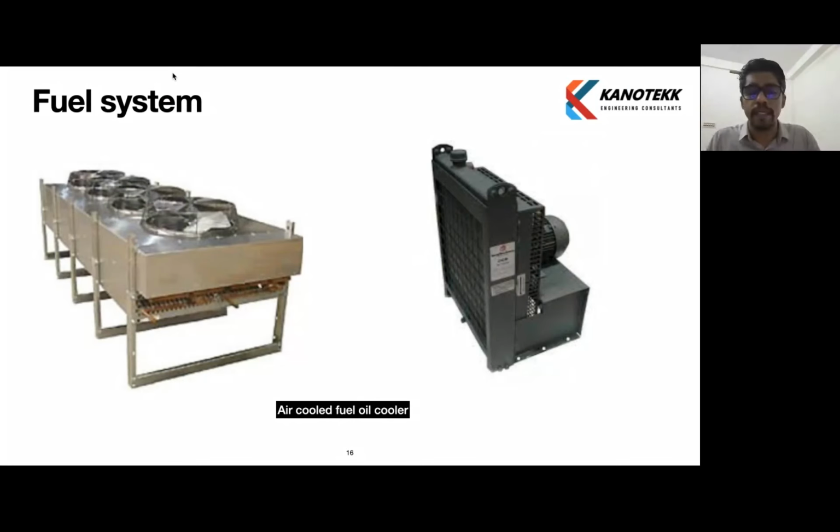Okay, what we are seeing is air-cooled fuel coolers. These fuel coolers, which we described earlier, are used on the return line of the generator fuel system. The generator fuel system return line passes through the fuel cooler where the fuel is cooled and put back to the day tank.